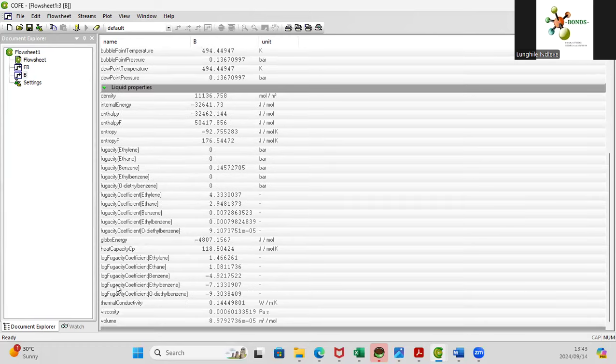This is all the information that you need to go and reference your property tables. Your simulator is now able to give you that specific heat capacity at that specific pressure and temperature based on, as we discussed, the thermodynamic property packages that you're using. So that is the advantage that you have.